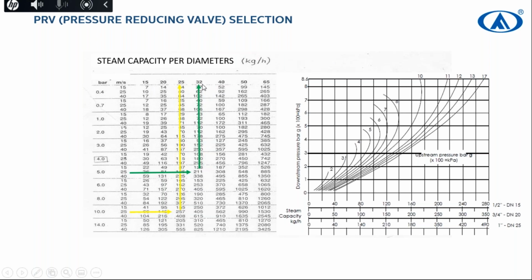And also, that's why in piping and instrumentation diagrams, in P&IDs, the pressure reducing valve's entrance triangle is shorter than the outlet triangle. That's why the inlet triangle is smaller than the outlet, as it's shown in drawings in P&IDs. So the inlet size of pipe is DN25, the outlet size of pipe DN32.